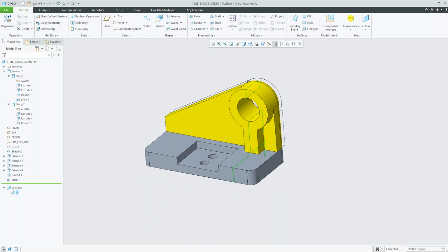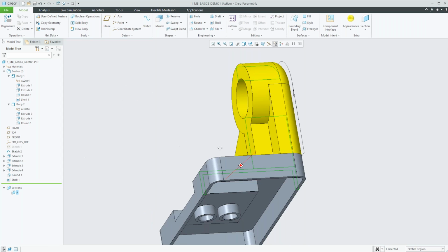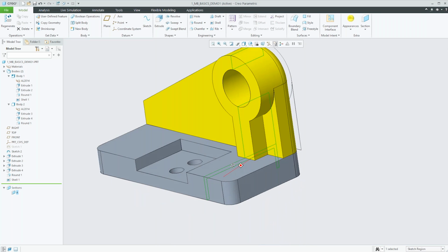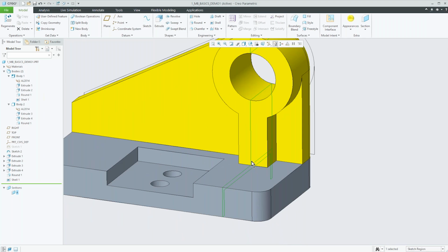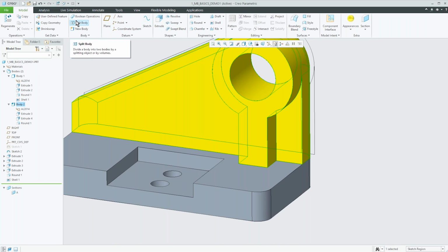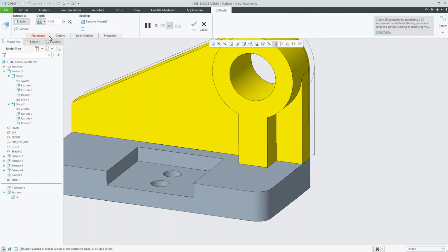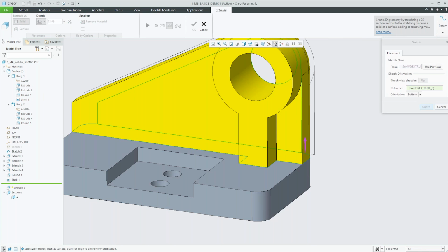So now that I have this, let's go and try to think about maybe how right now they're just sitting on top of each other, right? 2 separate parts sitting on top of each other. So maybe I want to kind of fit them together. I'm going to put a little peg in body number 2. So again, I'm just going to activate him and say, let's create a sketch, I guess. So we'll say, let's extrude, and we'll say define a sketch. You can pick on this surface.